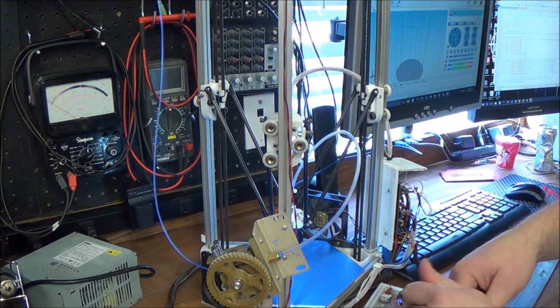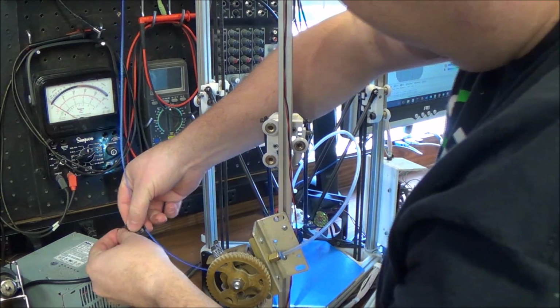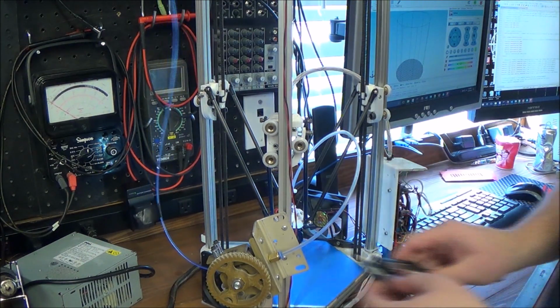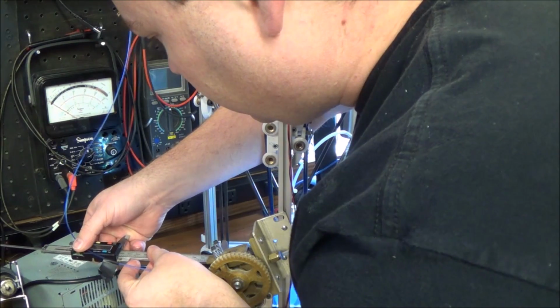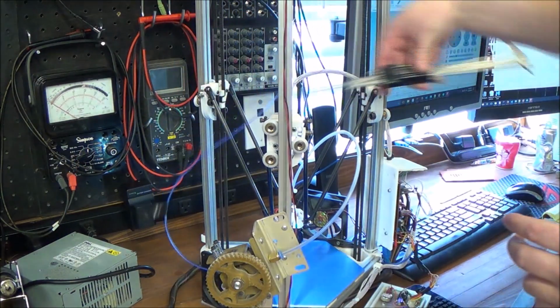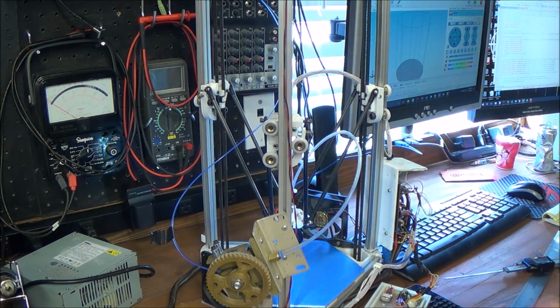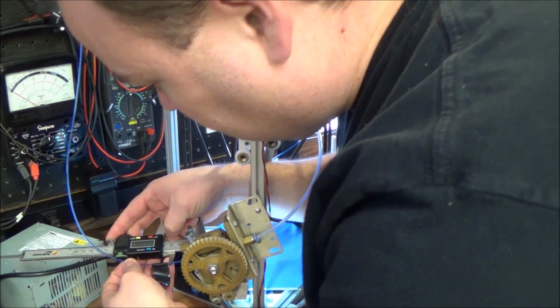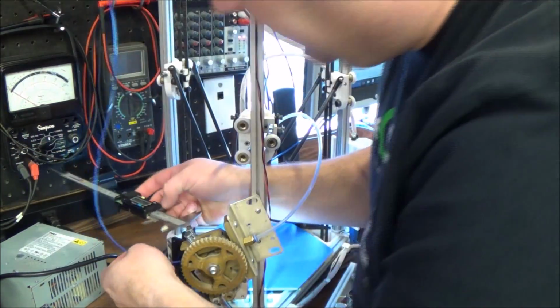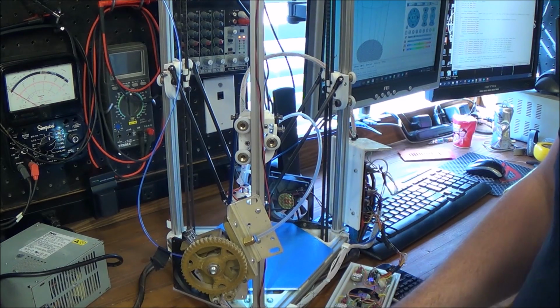So I'm going to do this, put some tape on here. And we're going to do the same type of thing. So we're starting at 120 exactly. Now I'm going to move it 100 and measure it again. Alright, so this says 34, which isn't good. It only moved 80 when we asked it to move 100.